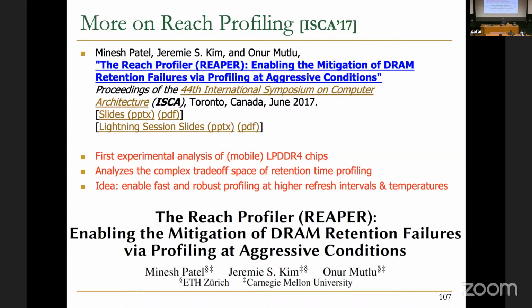Does it mean that we need more reliable memory alongside the DRAM, where we can store the characteristics? Yeah, that's a good question. Basically, where do you store this profile? In our work, we store it in the memory controller, so it's reliable. It's an SRAM in the memory controller, but that requires you to profile every time. But if you envision reusing the profiles across runs, then you need to store it somewhere, probably in storage, and then bring it back. NVM, yes, exactly.